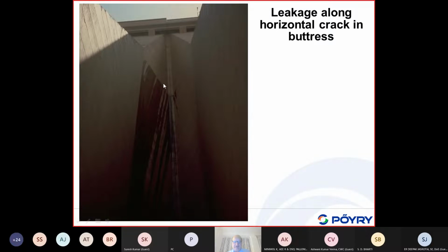It means that a crack has developed along this lift joint, and this crack developed not just 1 meter deep, it developed through the whole dam body. We see here a contraction joint, and here we have water stops, and this is the adjacent one where this crack doesn't really manifest in a way we see in this buttress.